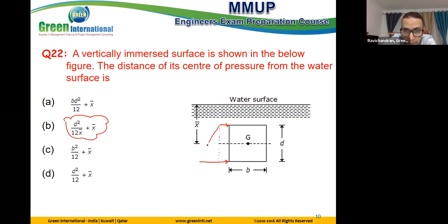If you check something like this, the pressure here is not the same. This is high pressure, this is low pressure. So the pressure here is not uniform. If the pressure is uniform and I ask what the equivalent force is, you tell me it is in the middle. But if it is not uniform, the equivalent is not in the middle.